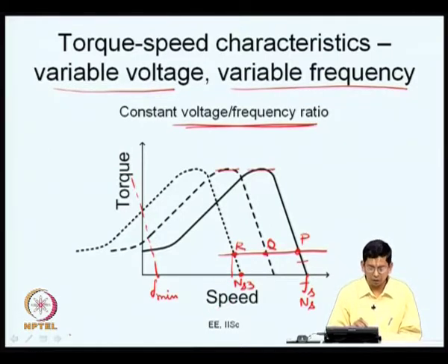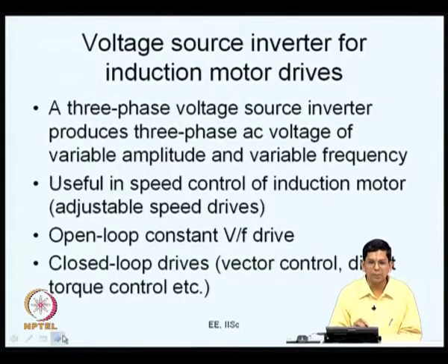And also you have several closed loop drive schemes, which, as I mentioned in the previous class, will be dealt with in other NPTEL courses exclusively on the subject of motor drives. That is an involved subject. For example, if you want high dynamic performance, you have drive schemes called vector control or field oriented control and direct torque control, etc. These require an understanding of how you model the machine for dynamic operation, and how you go about controlling them in the different frames of reference, etc. You can develop a good understanding by following courses in the area of motor drives.